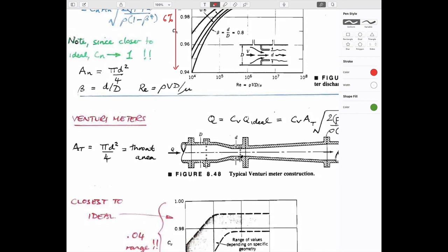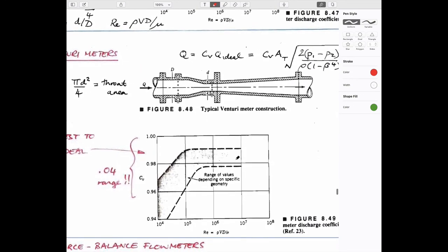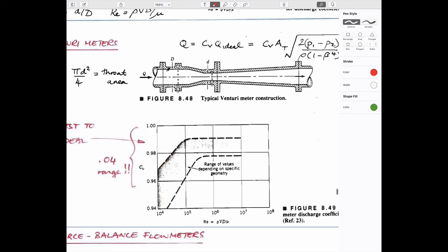And I guess the ultimate evolution of that is to use a Venturi meter, where now the flows, as you go downstream, cause no eddies to form at all. You're just hugging the pipe. And so it's kind of a laminar flow with the deck of cards, the laminae of fluid just skidding over each other. In that particular case, again, the range of these correction values is of the order of a few percent. It varies with Reynolds number, once again, and you measure pressures in the unrestricted portion of the flow meter and in the maximum constriction of the flow meter.